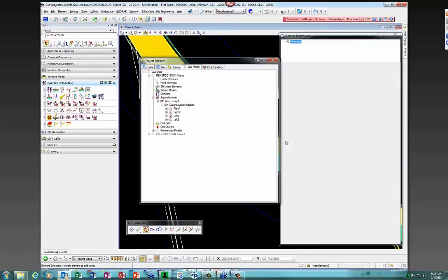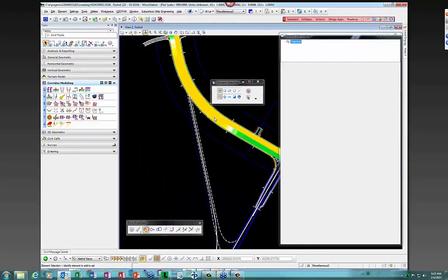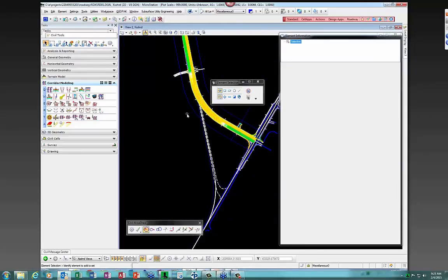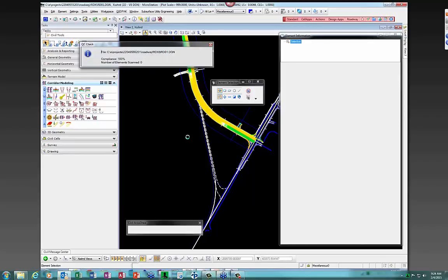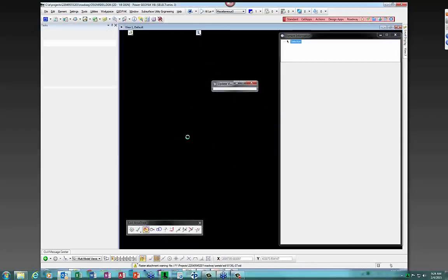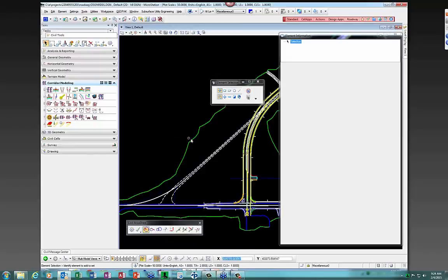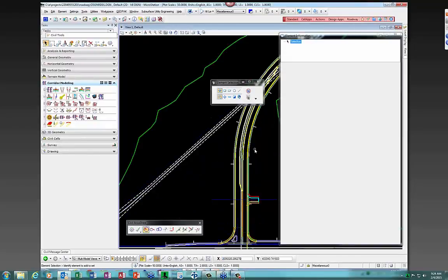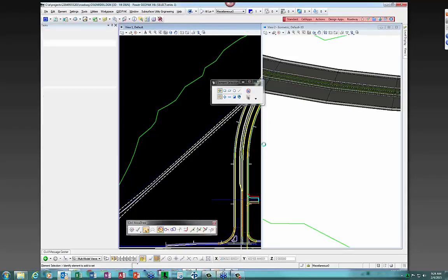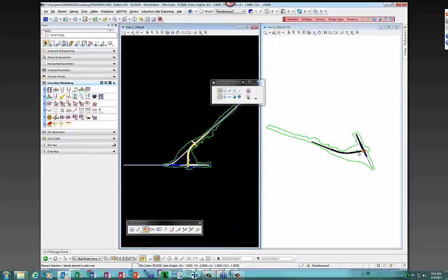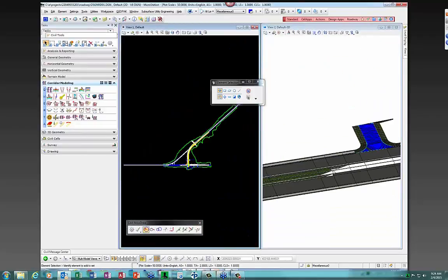Okay. Once you have your superelevation set up, it's calculated. It's all set up in this superelevation shapes file. Then you're going to go back to the design file, and you're going to assign it to a corridor. So far it's only been laid out based on the center line, and so it has no connection to what the corridor has going on with it. So far the corridor is just a 4-lane urban divided section that has no superelevation.